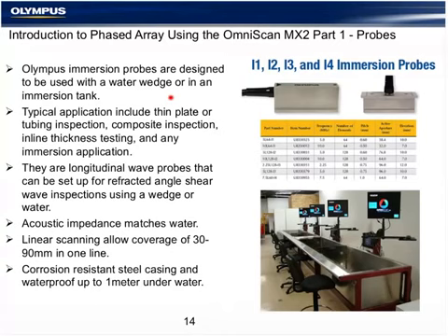Probes for immersion tanks would be very similar in construction, but would have an impedance matching layer for water. They're still defined by frequency, number of elements, and pitch. They typically have a much larger element count because they're used for coverage of composite aircraft inspection and large components. It's normally a speed or a race for productivity as much as it is an improvement over the conventional inspections.